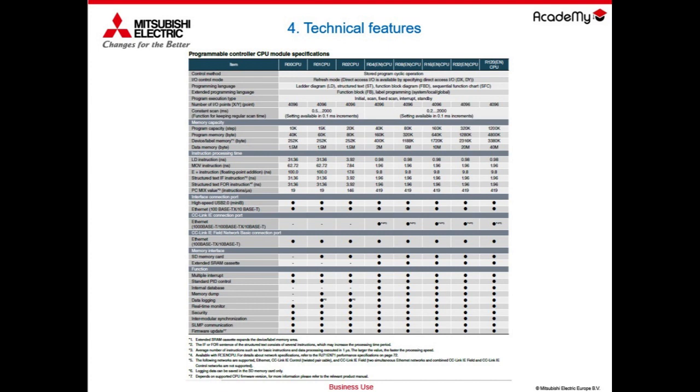However, in this case, they are identical or better from this point of view. There are no differences between the various CPUs. They can also be differentiated a little, as anticipated in the previous slide, for hardware and software function. For example, the SD memory card is not present on R00, or the possibility of extending with the SRAM memory. The memory for the device label option is not present for R00, R01, R02. So in fact, the suggestion is, where possible, always start from an R04.